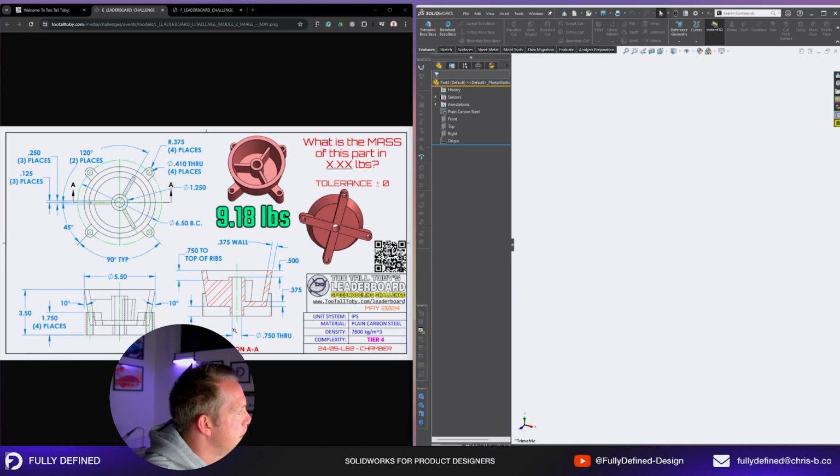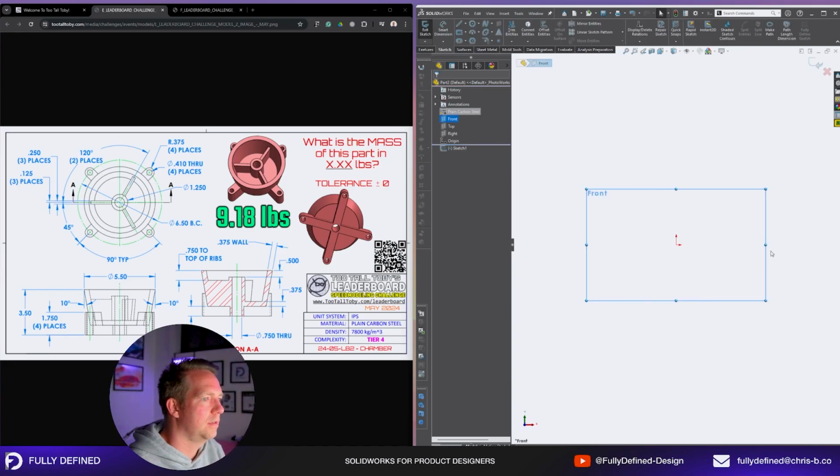And I can't see a dimension for doing it via an extrude. So you want a dimension of the bottom circle or the top circle. 10 degrees, 55.5, 10 degrees down, and it's going down 2.75. Could do that. And then shell, I think maybe it's just do that whole sketch profile. So do this section view, sketch profile, revolve it, and then you do your other two extrudes and work out a very efficient way of doing them. So let's give that a go.